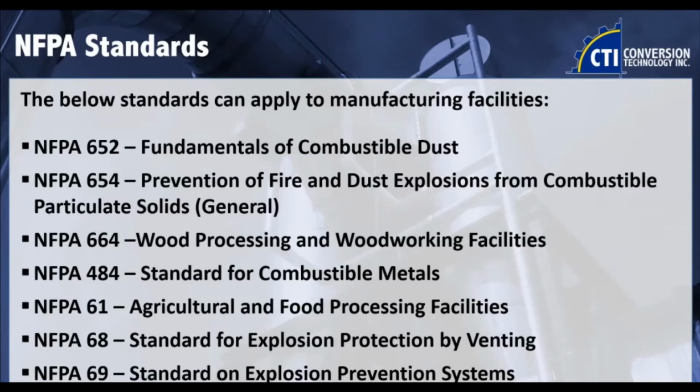Now that gets superseded for those of you that might be in agricultural and food processing, where NFPA 61 is what's called a commodity specific standard. So NFPA 61 is the prevention of combustible dust issues in agricultural and food processing. For those of you that deal with feed or flour, sugar, food plants, whatever that is, your deadline is going to be September 1st, 2022 for conducting the DHA. I will get more in depth of what that means in my DHA section of the slides.